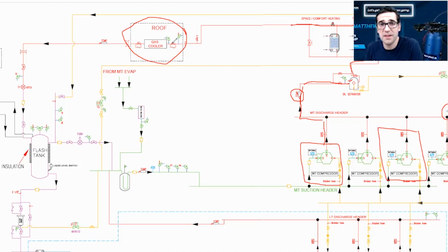I've installed the same system 6 times, but that day, whoever was working on the floor of that manufacturer made a mistake. Maybe put the wrong part on, put the wrong pressure transducer, put the wrong component on, which happens. But me as an installer or commissioning or startup guy, I need to do that verification. I can't blame anyone but myself if something happens. A component fails because I didn't check before.